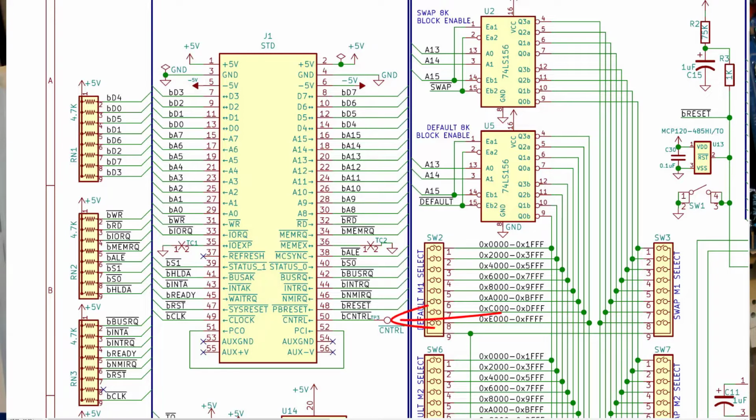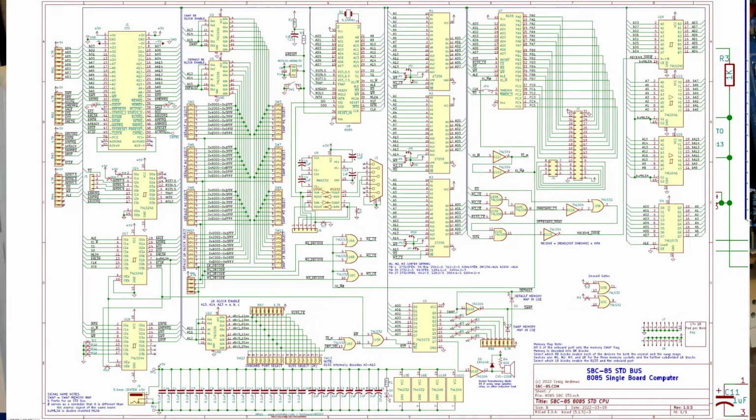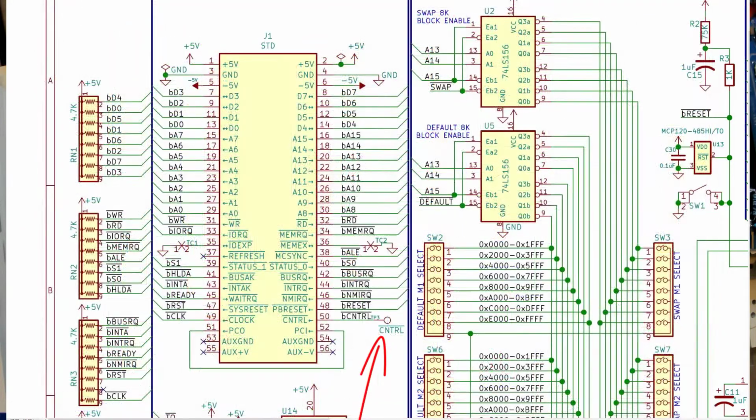It's specified as active low, but other than that, it should be considered a proprietary signal, maybe a system tick, a watchdog tick, some sort of a gating signal. The user may want to connect the timer out into this line or maybe bring it into an interrupt. So it's brought out to a test point where the user can install a wire wrap pin and jumper it however they see fit to whatever on the board.